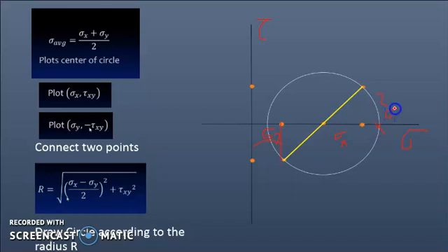If we draw based on the scale, we can measure this value, and that value directly gives us sigma 1. That intersection point is sigma 2, which is the minor principal stress. Then the angle between these two is 2 theta, which gives the angle of the maximum shear stress.